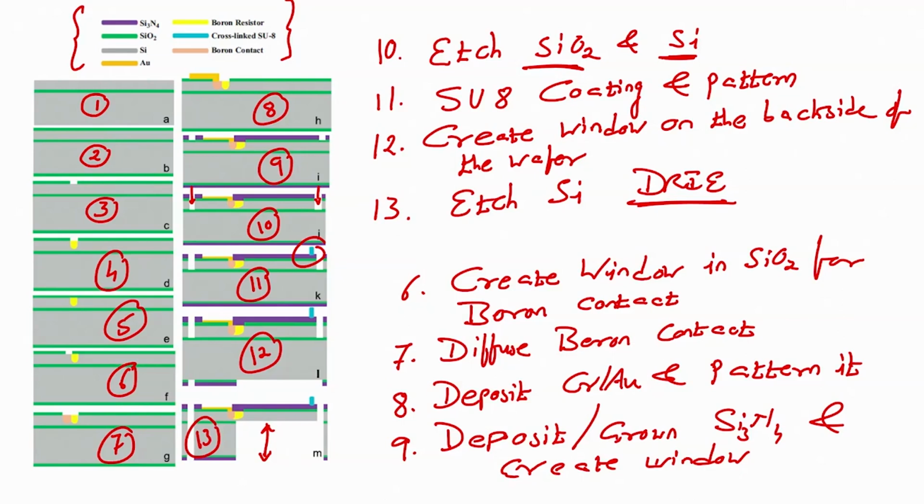Another thing that we have observed is, we are using boron as the piezoresistive material, and the silicon that is on insulator is our polysilicon, or it can be single crystal silicon. The point is that you can also grow silicon on insulator and perform the experiment and evaluate its performance with the cantilever that you can make using silicon on insulator, which is single crystal silicon.